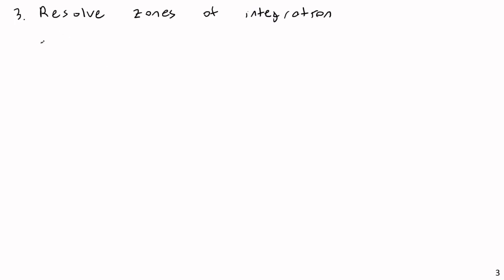So if I do that, I'm going to need to break apart the moment from the real loading. I'm going to need to break up the second zone, which currently has one zone between 5 and 15. I'm going to break that into 2 zones of identical expressions.